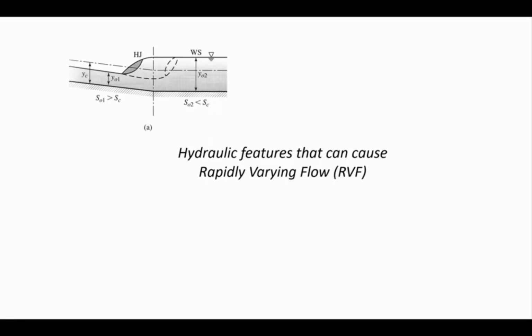And if you've ever gone whitewater rafting, maybe you've seen a hydraulic jump. I've done it a couple of times on both the New River and also the Gauley. You can see these usually behind a steep drop. There's a standing wave. Hydraulic jumps can occur when you have a steep section that then goes to a flat section. I think that's what's happening, at least in the locations I've seen on the New River: there's a big drop down and then the standing wave forms after that. Here it's showing it can be before it or after it, depending on the relative magnitude of the slopes. So this is one thing that can cause a hydraulic jump.